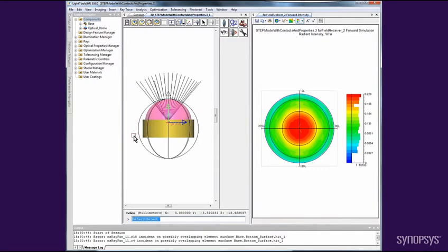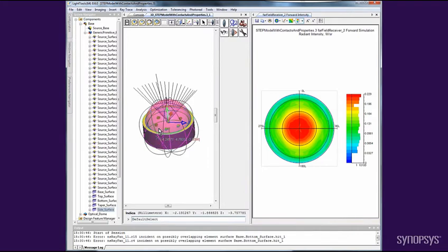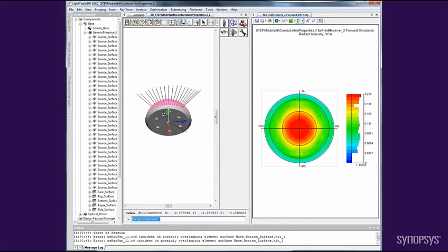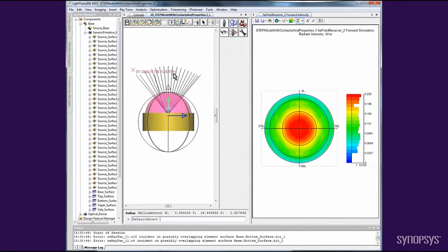To demonstrate the importance of the optical contact setting during simulation, we'll start with a model from the LightTools example model library. In this model, there are two imported objects. The base has 7 protrusions, each representing an LED, and the dome has a cutout that fits over the base. Our goal is to make sure the appropriate surfaces are contacted together. Right now, LightTools will assume there is a small gap of air between these two entities.